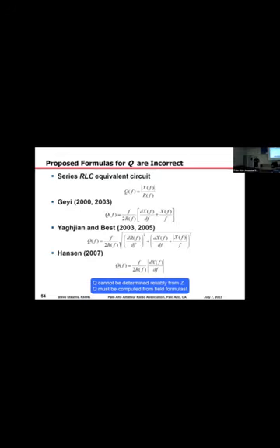We can build those structures into the antenna as part of the antenna, and in that manner, we can cause the reactance to go to zero, the derivative of the reactance to go to zero, the derivative of the resistance to go to zero, and every one of these formulas will give you zero. So the Q of the antenna, I've given you four ways to make a zero Q antenna, four different strategies, so that you can make an antenna that at its feed point looks like it has 0 Q, yet it really won't have 0 Q, but it will look like it has 0 Q.